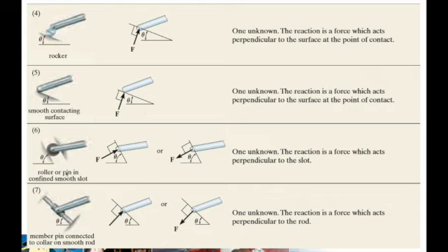So if you have a roller or pin in a confined smooth slot, this is your reaction force, either compression or tension. If you have a member pin connected to a collar or smooth rod, this is your reaction force.